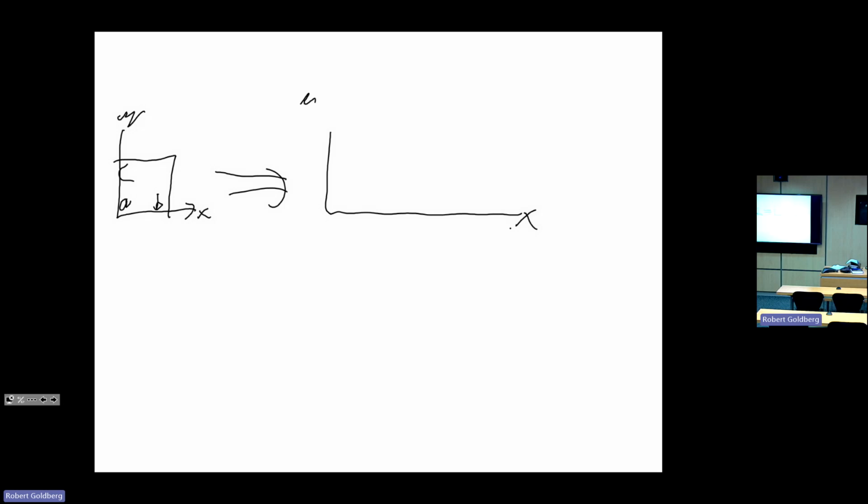After deformation, we have still our x and y axes, but now we've applied some sort of force along the x direction, and we've stretched it out. Now, point A is at A prime, which is still at the corner, but we have B prime and C prime, which are the new locations of points A, B, and C after deformation, and this is x prime and y prime. So we've deformed this cube, and so it started off here, it moved to here, and the locations of A, B, and C are now at A prime, B prime, and C prime.